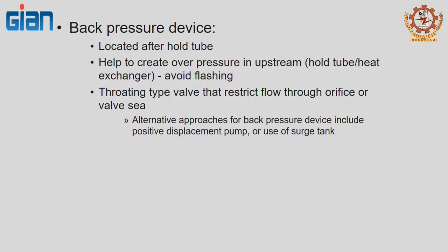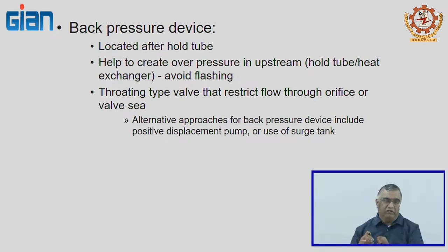Now, I talked about the aseptic processing temperature being 130 to 140 Celsius. If you remember, water becomes steam, it boils at 100 Celsius, whereas your product here is being processed at 130 or 140 C. So, how do I maintain the product in the liquid state in my holding tube? This is where a back pressure valve comes in.